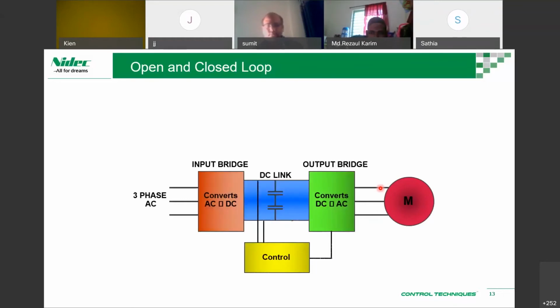Okay, so it's interchangeable. VFD and VSDs are the same. Okay, so we have this. Earlier we just saw converting from AC to DC, and then we have a DC link, and then the output bridge. So this is all what we saw, but we didn't have any controls. We just had in and out, that's it. But we still need a control to switch properly so that we get that PWM control in a controlled manner.